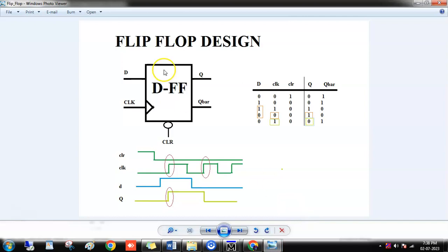As per the design, we have different types of flip-flop, starting from SR flip-flop, JK flip-flop, D flip-flop and T flip-flop. D flip-flop is the commonly utilized flip-flop in all kinds of VLSI systems, since for the triggering operation to work, only one input is enough. In SR flip-flop, we have a forbidden problem, and in JK flip-flop, we have the toggle problem at the 1-1 condition. Hence, finally, the D flip-flop with one input is the recommended and foremost best flip-flop for digital systems.